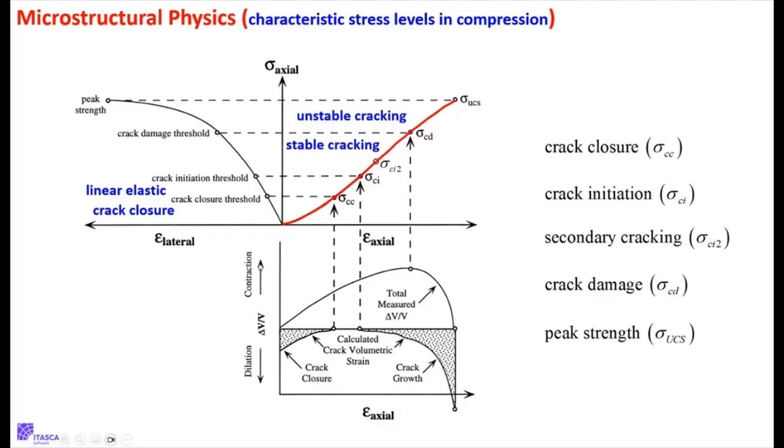He set up his UCS rig, just his standard UCS rig, and he slowly applied axial strain, just like this. But when he reached this point, and he knows he reached the point because he's plotting this curve that he's measuring, when that curve starts bending over, he then would hold the load constant. So he turns off the mechanism that's applying strain. He stops the motion and he turns on the mechanism of the servo machine that maintains constant load. Okay. And well, that's fine. It should just sit there.